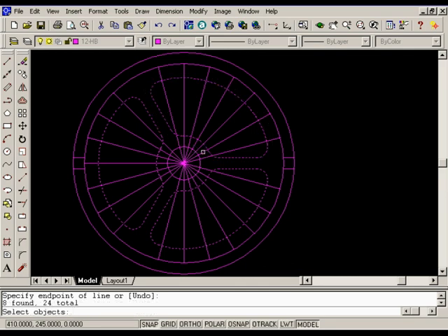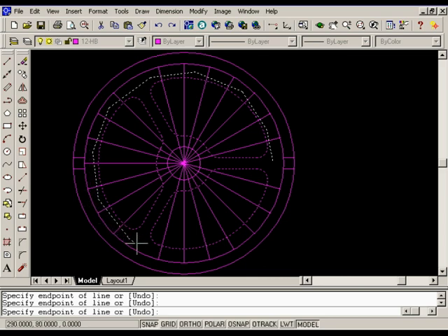At the Select Objects prompt, press Enter to indicate that you do not want to select any more objects as cutting edges. At the next prompt, enter F to specify a selection fence. At the following prompts, click points to specify a fence completely around the outside of the elements of the array and inside the larger circles. Only objects that are crossed by the selection fence are selected. Press Enter to trim these lines.